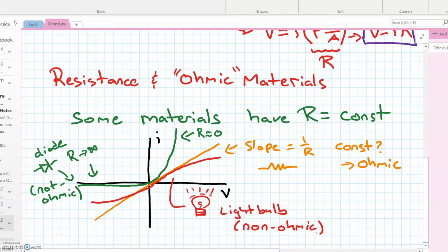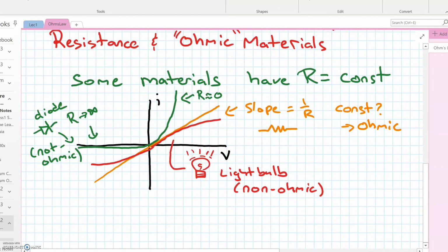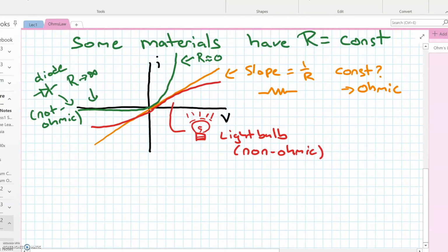Okay, so we have things that are ohmic and things that aren't. Things that have a linear relationship with respect to voltage and current, and things that don't. Now, in nature, pretty much nothing is actually linear. Effectively, if things are linear enough, we call them ohmic. We can still define the resistance of something that is not ohmic. We can do it in a couple of ways, though.